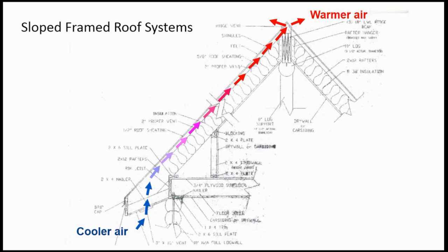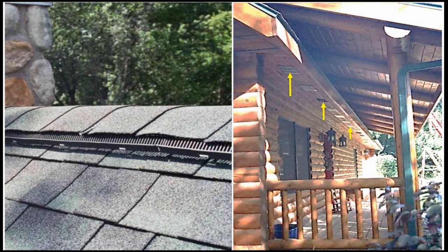This is actually a wintertime condensation problem we had in a sloped roof, and I'll explain in a second. We had soffit vents and ridge vents, and they were working well. What actually happened in this case, and we didn't figure it out until a little later, was that underneath that deck that you see in the image, there were exhaust vents from two very large dryers.